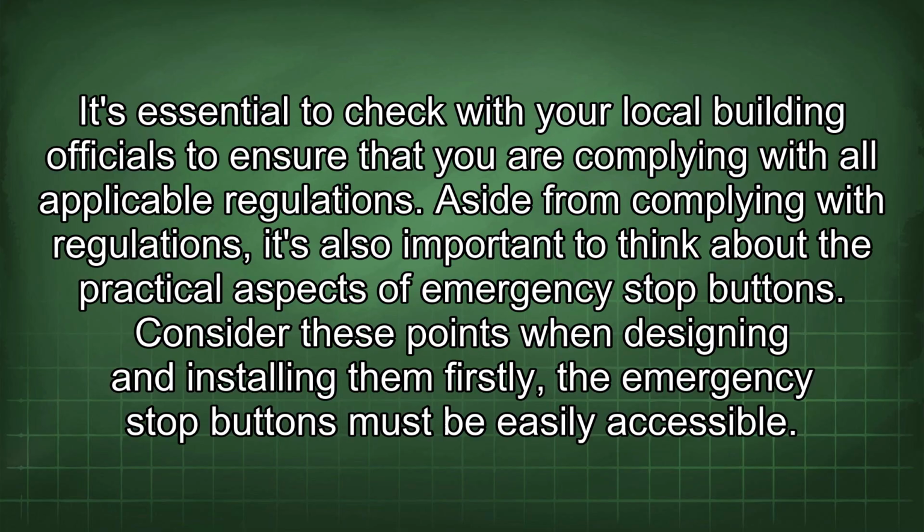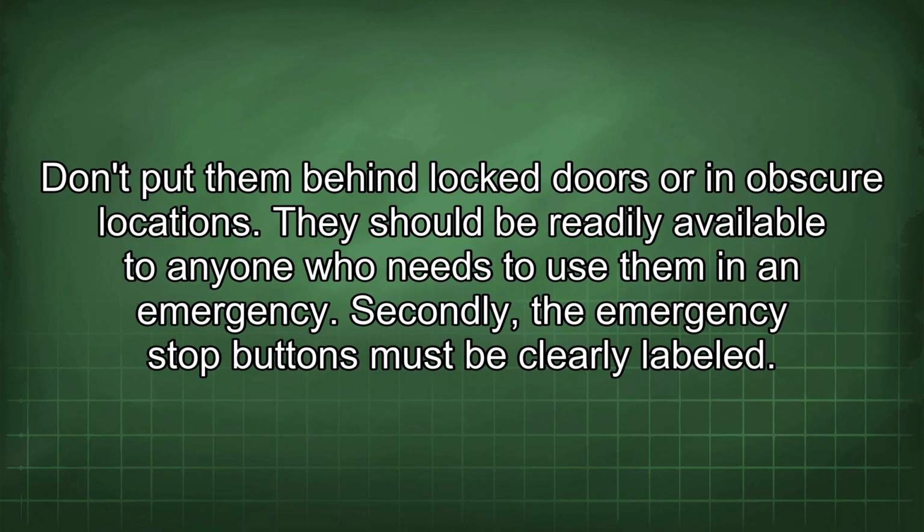Consider these points when designing and installing them. Firstly, the emergency stop buttons must be easily accessible. Don't put them behind locked doors or in obscure locations. They should be readily available to anyone who needs to use them in an emergency.